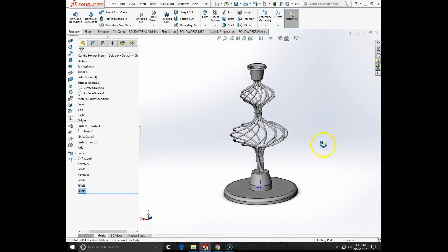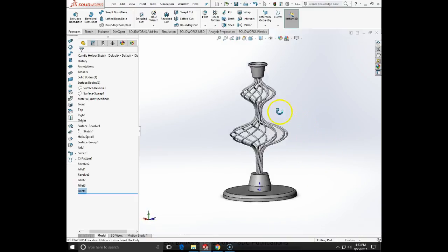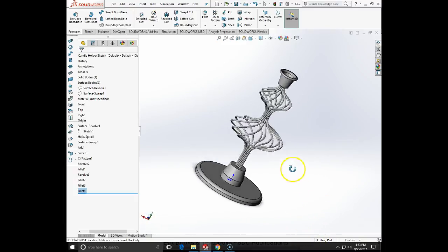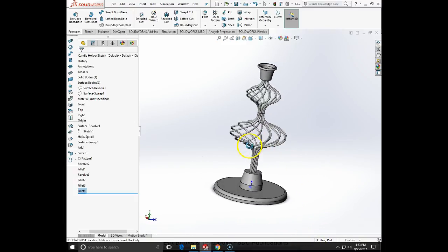And here is our chandelier, fully defined and completed as a beautiful model, which is fully parametrically defined. We can change its shape by changing the parameters of the helix and the parameters of the profile of the revolved object. So we've seen how we can use the surfaces to create the derived intersection geometries, and then we use those intersection geometries to drive creation of the solid object. And this concludes this demonstration.